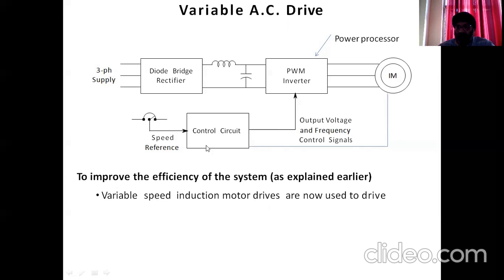So the difference of these two signals will be calculated by the controller, and the difference is sent over here. And now the switching frequency of the power inverter will be changed or adjusted, and we get an actual value of the speed of this motor same as the required speed over here, just by making the difference of this and this. Sorry, this signal and this signal.